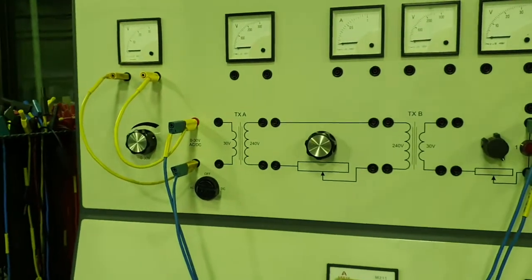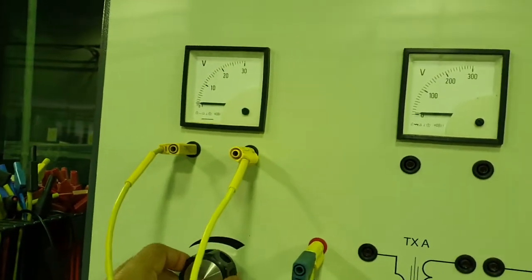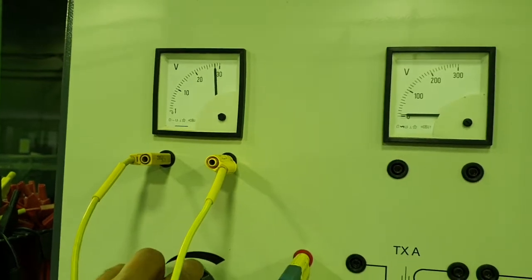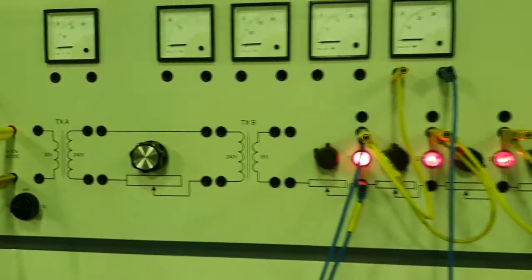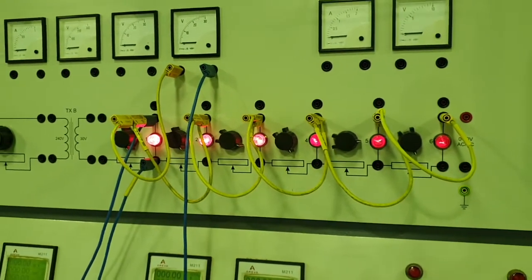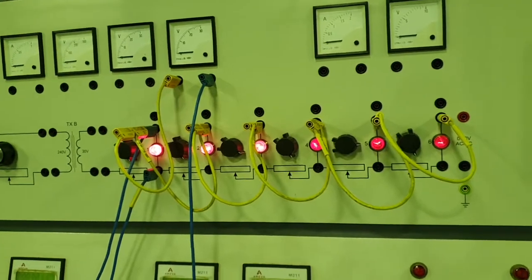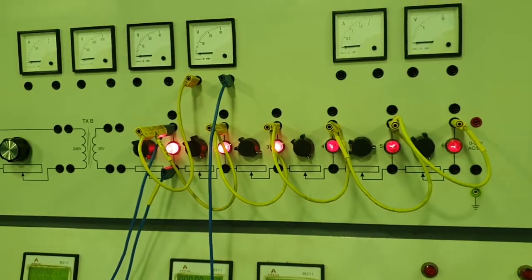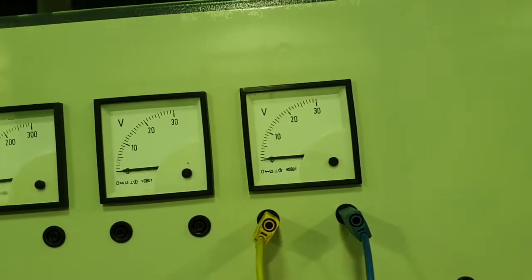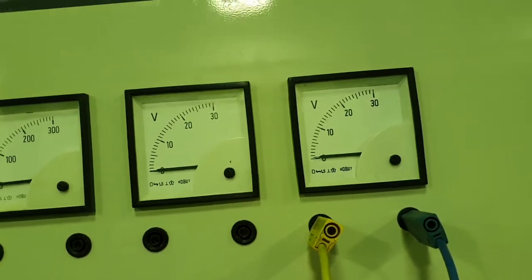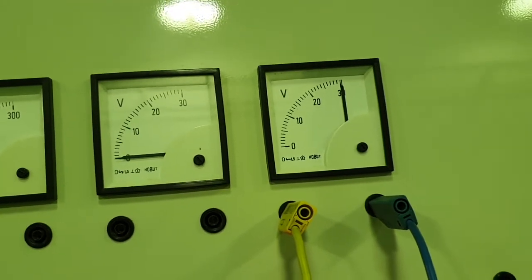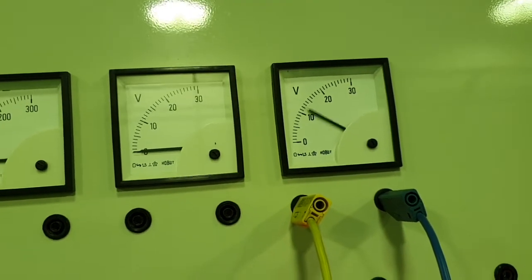So what we have to do is first apply 30 volt AC. Now you can see all loads are on, but see the difference in the light. This difference in light is because of change in voltage, because voltage drop happens throughout the line. As a first experiment, we connected this voltmeter here, and we will see the voltage at the first load. At the first load the voltage is 30 because it is at 0 distance. If the distance is 0, there is no voltage drop.